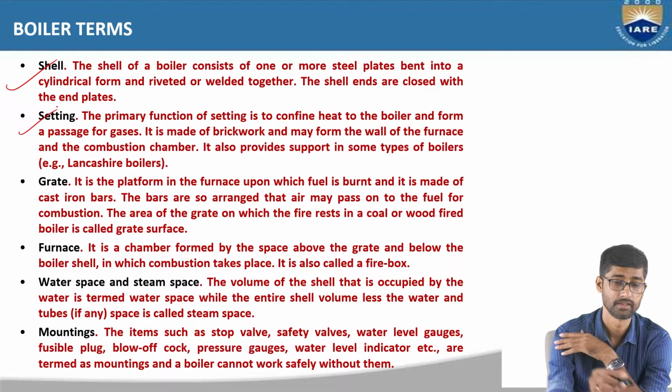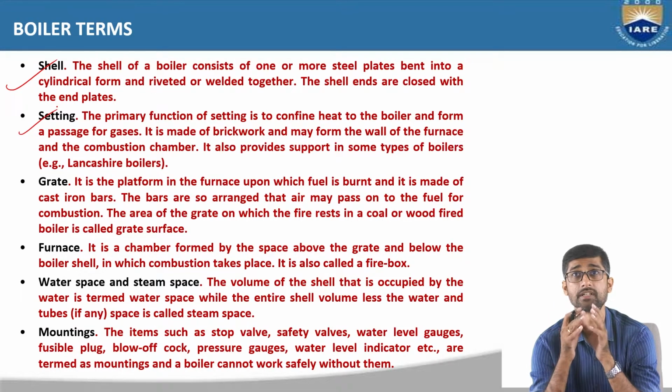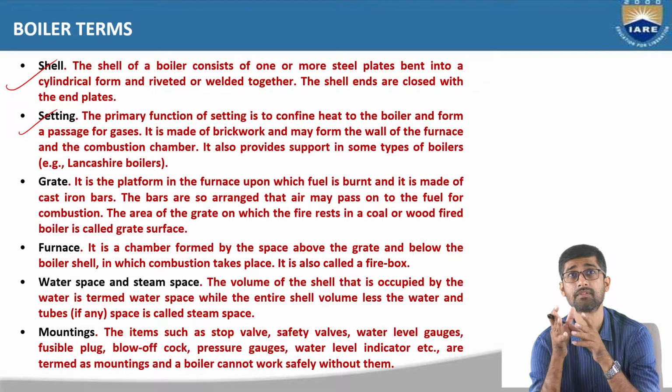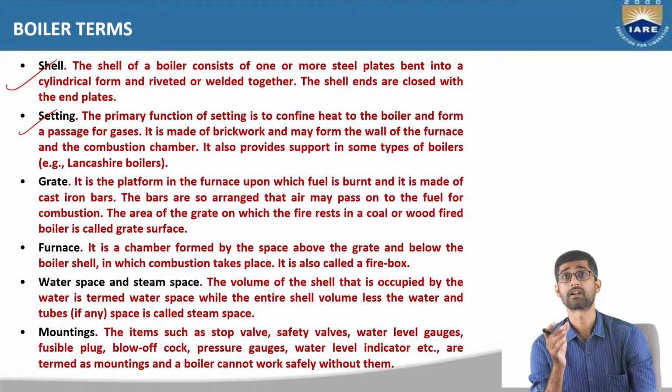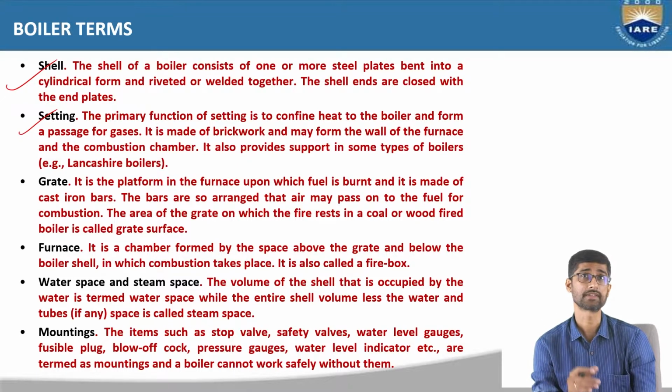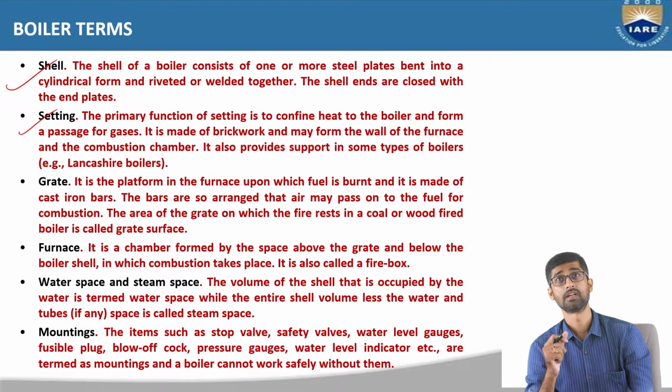Next, setting. The primary function of setting is to confine heat to the boiler and form a passage for gases. It is made of brickwork and may form the wall of the furnace and the combustion chamber. It also provides support in some types of boilers, for example, the Lancashire boiler.